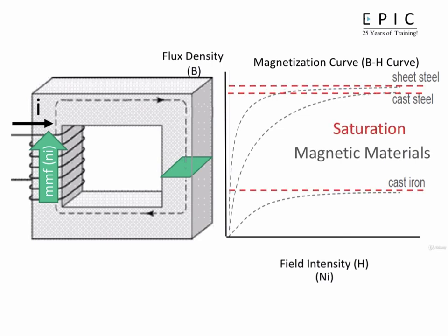This flattening of the curve is known as saturation, and is characteristic of what happens in transformers that are wound on a magnetic material. Most transformers are designed to operate in the linear region of the BH curve, but at times they are pushed into the nonlinear regions of the curve, which could produce problems that we'll have to deal with, and we'll see those a little bit later.